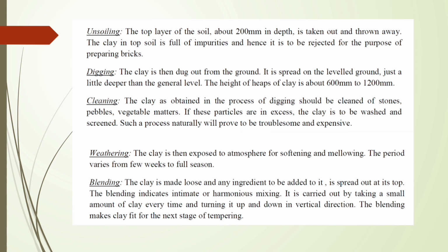Cleaning. The clay as obtained in the process of digging should be cleaned of stones, pebbles, and vegetable matter. If these particles are in excess, the clay is to be washed and screened. Such a process naturally will prove to be troublesome and expensive.